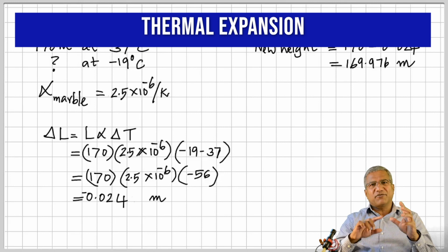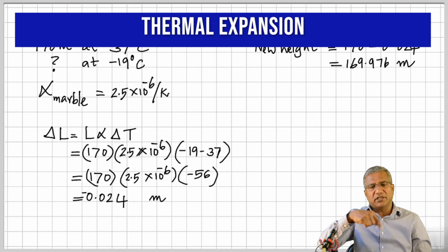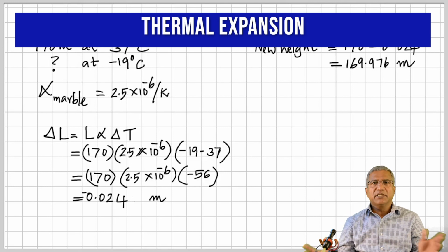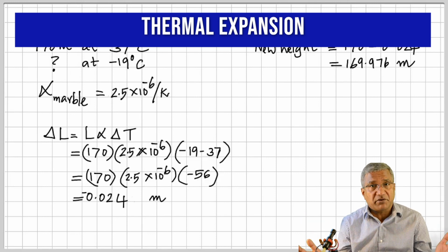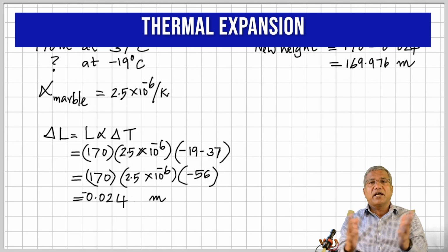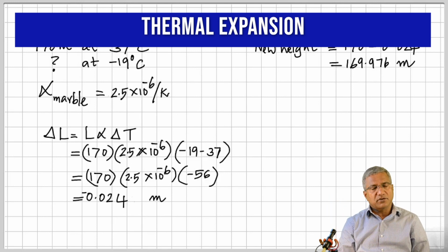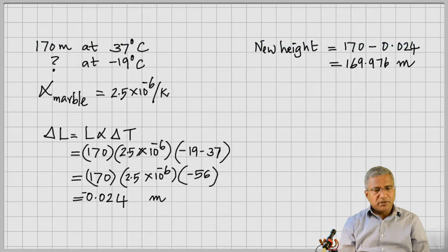And the proof is, instead of cutting it out, if you had just taken that metal plate and drawn a circle on it with a marker, don't cut it out, just draw a circle. Now heat it, what will happen to the size of that circle? Now everybody will say it'll increase, correct? Same thing happens. So whether there's material inside the hole or not, it's the same thing. So remember that. That's a really difficult question for anybody to answer. So that's about linear expansion.